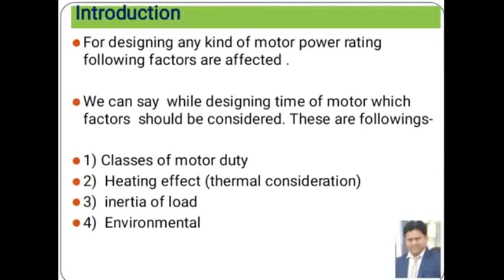Third, if a motor is selected with a higher power rating, there will be extra cost, that is, it is uneconomical. And last, if an appropriate motor rating is not selected, then there will be chances of short circuit due to damage of the winding insulation.